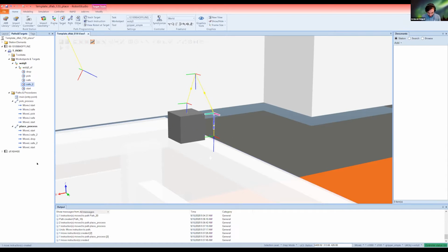But do you remember from the last time we were talking about different move J's and move L? Basically, for this part, you could go with move J, with V maybe 200, with Z of 0 or 10 or whatever. And for the rest, we would go for move L, V like 10, or maybe like 50, and Z 0. And for this one, L, V 10 is even fine. So you need to also edit these parts.